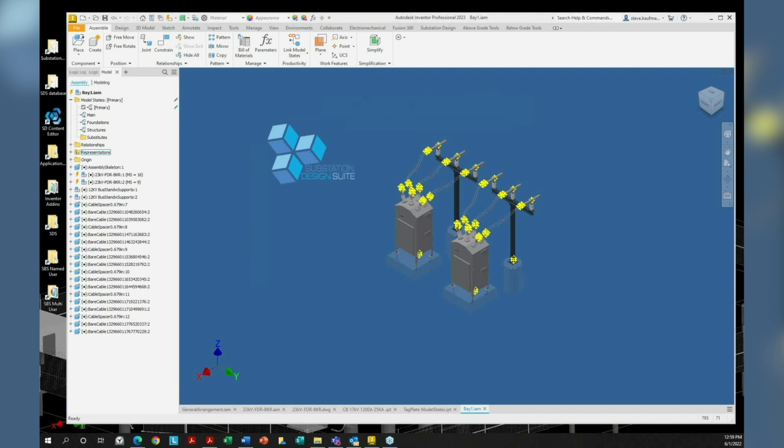Yeah, if you start linking the model states from the top assembly, I think you could run into a complexity issue. It might be a little too complex. I'd much rather be at the smaller level, in the island subassembly and the part subassembly, in case I want to use that island in another assembly. If I start pulling that island out, I won't have those states. I want to keep it all in the individual island myself. So I have that model state there, and I can use that island in any other station I bring it into. I have it all already pre-prepared.